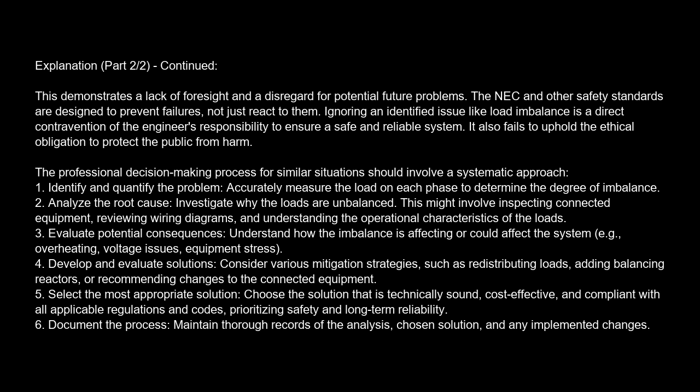3. Evaluate potential consequences. Understand how the imbalance is affecting or could affect the system, e.g., overheating, voltage issues, equipment stress. 4. Develop and evaluate solutions. Consider various mitigation strategies, such as redistributing loads, adding balancing reactors, or recommending changes to the connected equipment. 5. Select the most appropriate solution. Choose the solution that is technically sound, cost-effective, and compliant with all applicable regulations and codes, prioritizing safety and long-term reliability. 6. Document the process. Maintain thorough records of the analysis, chosen solution, and any implemented changes.